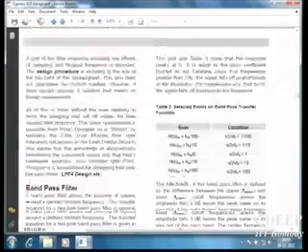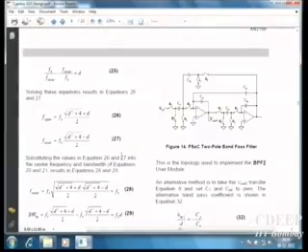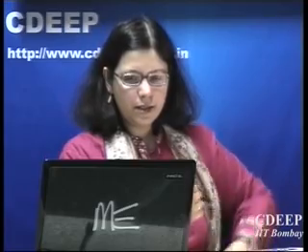simulator associated with it. Now the question is how we can simulate switch capacitor filters. See, in old days when we had only transient analysis available, one way, in fact, just recently also we were using, was to sweep frequency, not in AC domain, because it's a switching circuit. So you need to apply a sine wave at a particular frequency and then simulate at a sampling frequency, get value of output, amplitude at the output, repeat it for another frequency and so on. But this will take a lot of time, right?